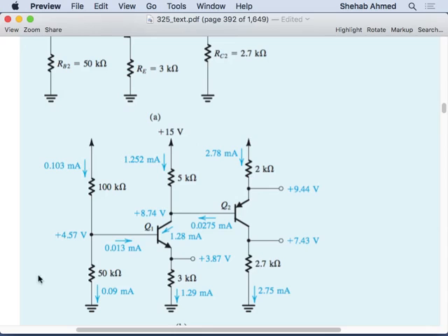So your sensor was here, right? Your sensor was outside this amplifier, right? And then this is your new output, right? So I've been able to construct a device with much more gain. You see now why op-amps are made of many of these devices? If you want to create something with a very large gain, you have many of these devices inside the op-amp, right? So that's one thing I wanted to show.